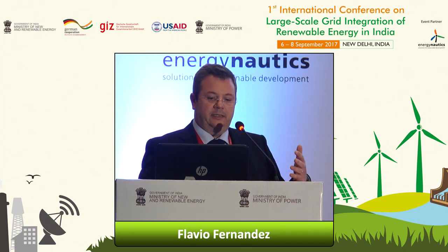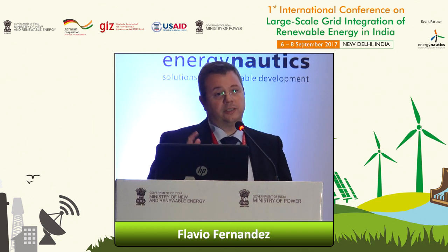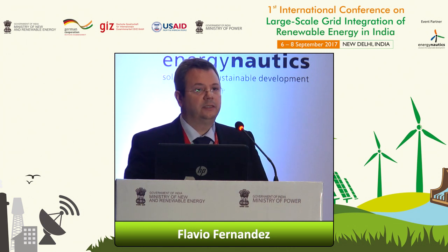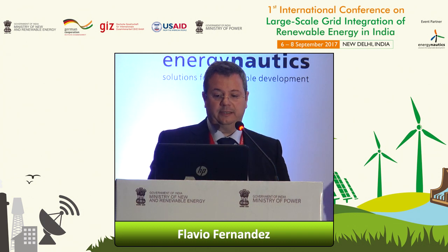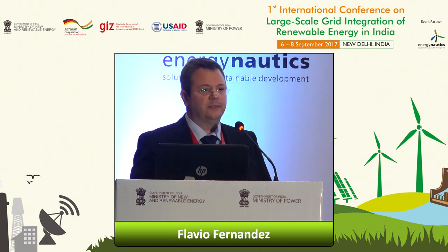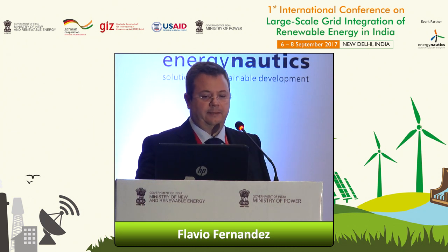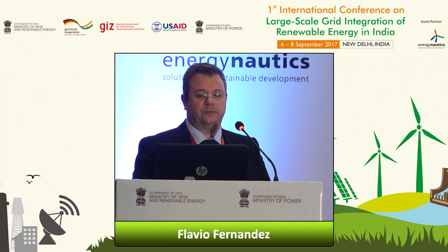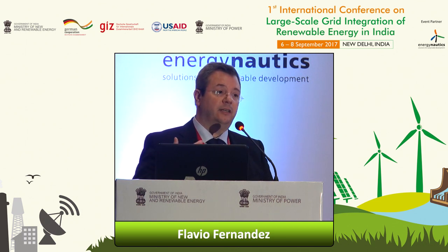Again, the cons: manufacturer specific, so black box representation, I should say not for all of them. There are different wind turbine manufacturers whose models are open, so you get a highly detailed model even as an open model. And again, the limited portability. Graphically, the model will look like this. In that case, you do not use the IGBT switches, but instead a PWM converter, which is an equivalent voltage source.